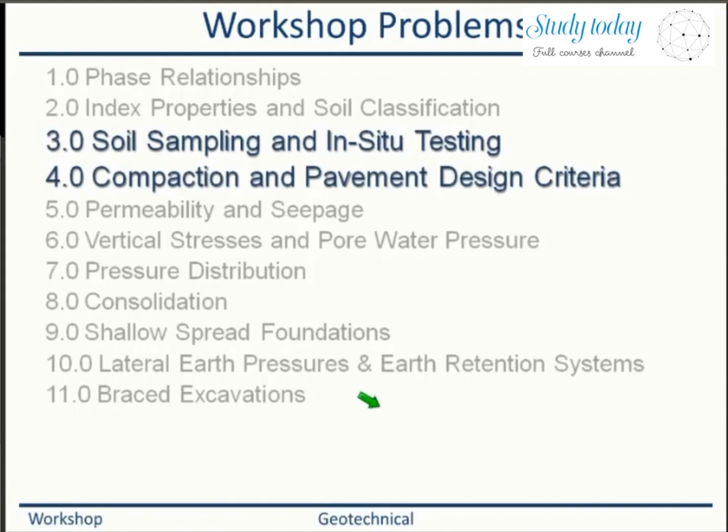Yes, I'm sure. First, the geotechnical report should be citing that. This is the thickness of the clay layers and the clay content of this kind of clay minerals, and this has a potential of swell. If you do construction on this type of swelling soil, your building will be heaved. Your building will be pushed up.